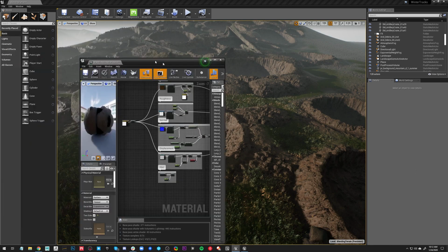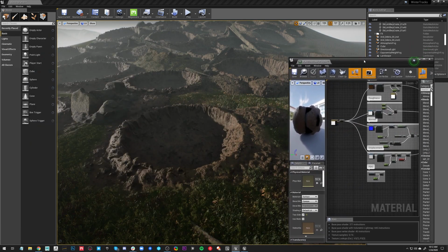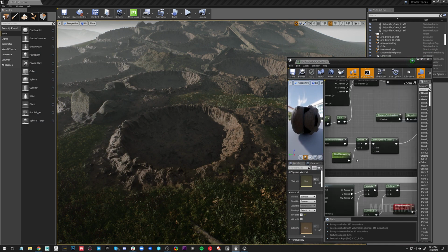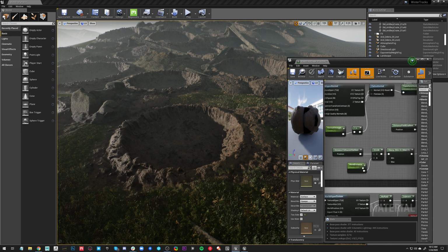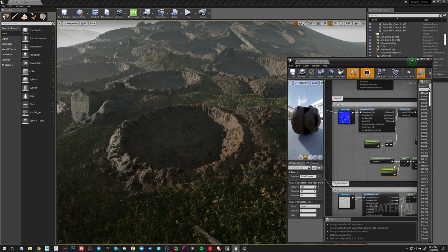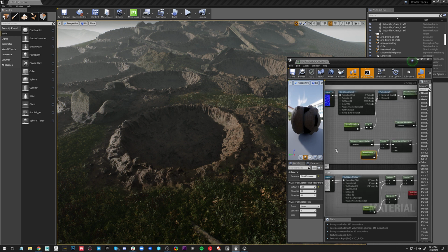All right. So as you can see here, let me just display what's happening real quick. Right here we have blend distance, and I will go over how everything is happening here. But basically what this is doing is taking the intersections, wherever this mesh intersects with something, it's going to blur the normals, and it's going to try and average those normals against the other surface.